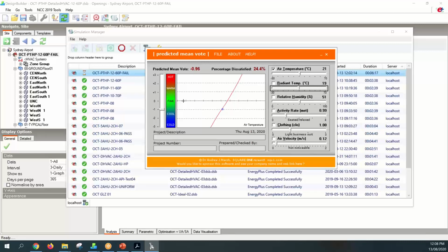Now, just to go back a little bit, when PMV was developed, as I said, it has to do with the voting system, and it talks about the percentage of people who are dissatisfied in a space. So when you get to about -1, about 24–25% of the people in the space don't actually consider that to be comfortable. That's the limit that's being allowed for in the code.